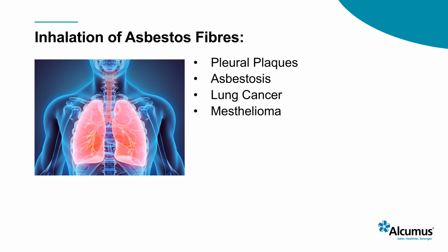Blue and brown asbestos are considered to be the most dangerous due to their needle-like fibres that can penetrate the lung tissue, whereas chrysotile is considered to be the least dangerous due to its serpentine, silky S-shape, which is less likely to remain lodged in the lung tissue.